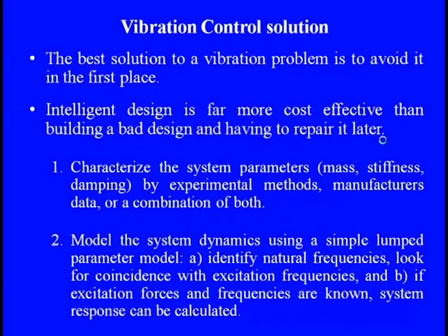We can see what kind of coincidences there are with the exciting frequency, and if the exciting forces being generated and their frequencies are known, the system responses can be easily calculated. Once you calculate these system responses, you can decide how to design and what kind of isolators are to be placed there.